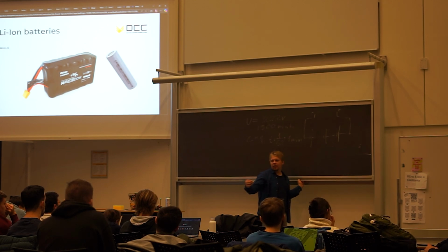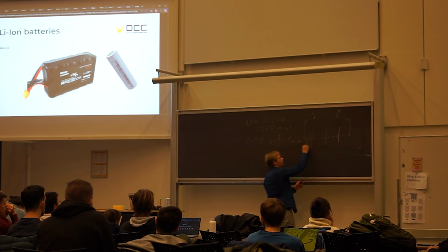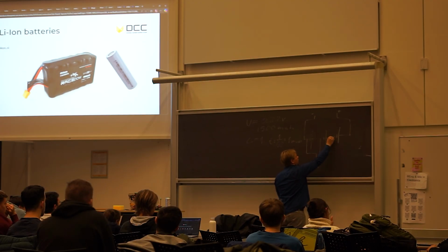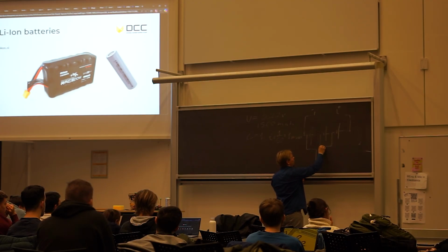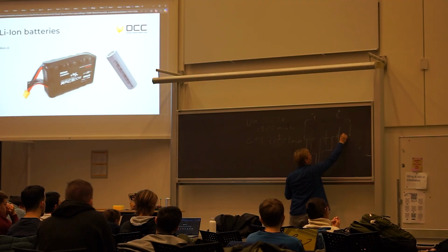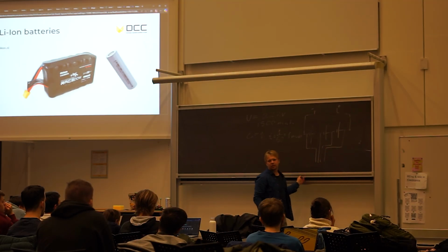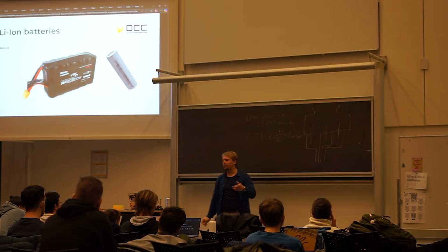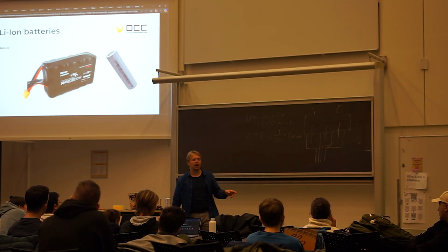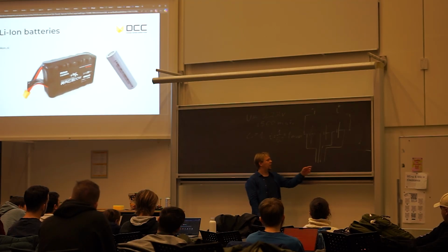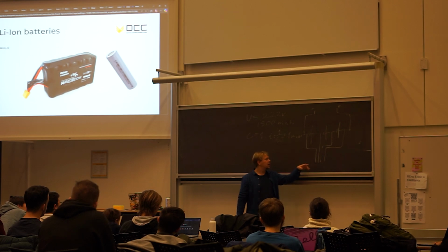And then you will have another lead, we call it the balance connector. That has every single one of the connections to accurately measure the voltage between the cells, so you can charge them balanced. The chargers that we use are balance chargers. You have to plug in both of the leads to be able to charge them.